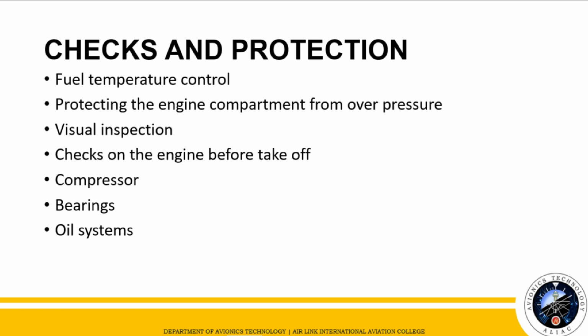So bearings need to be checked before and after flight because bearings can be loosened due to the friction and vibration mid-flight, and sometimes bearings are overtightened, which may damage the engine or the system that needs its bearing.